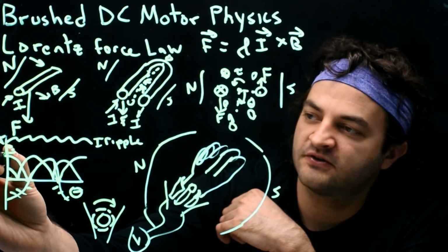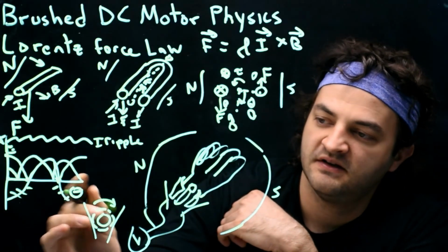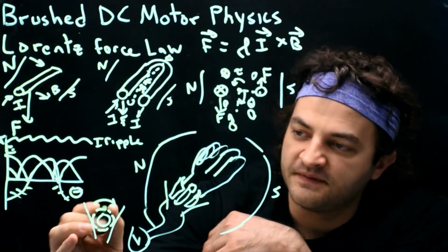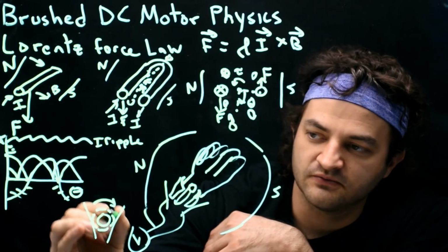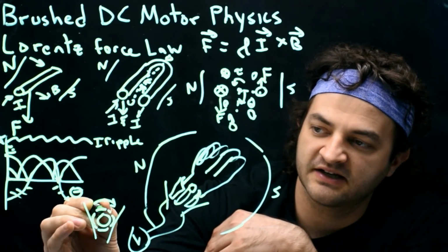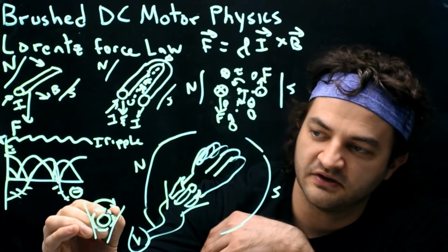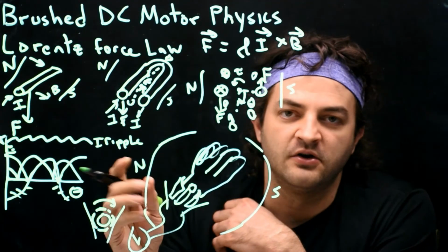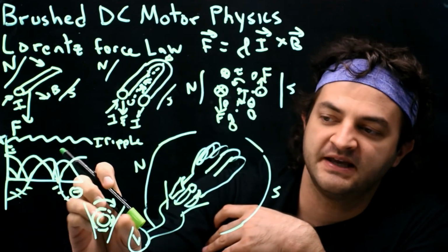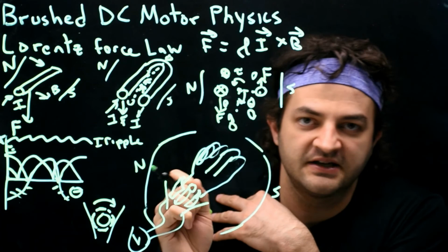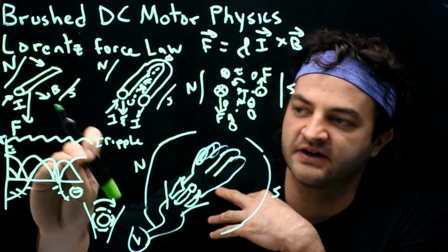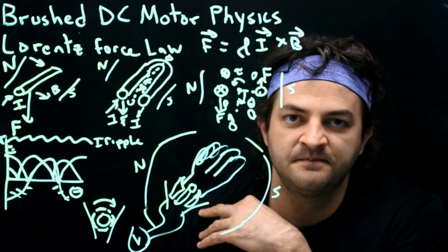As the torque starts to go down, because the coil is no longer well aligned with the magnetic field, this commutator is rotating. So this section would break contact and make contact with this one as it rotates over here, and this one would make contact with this one. So the act of the torque making the rotor spin makes the brushes make and break contact with the commutator segments, applying current to the different coils in the correct direction so that we always get positive torque.